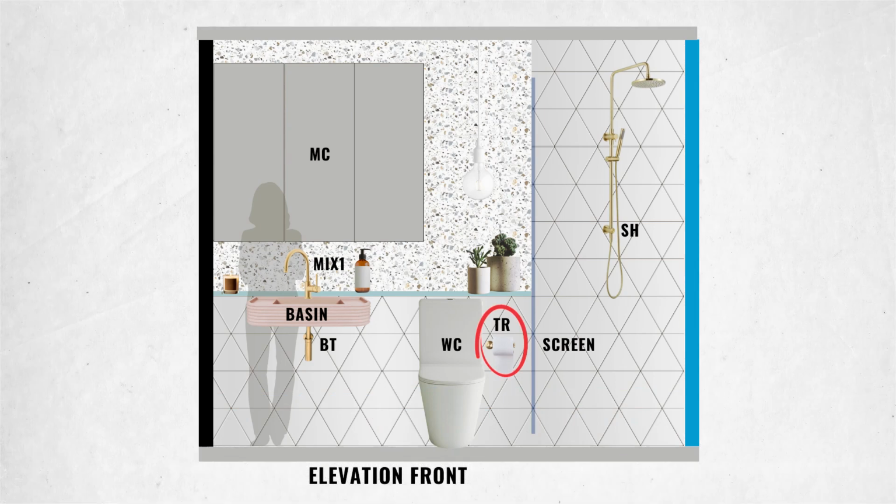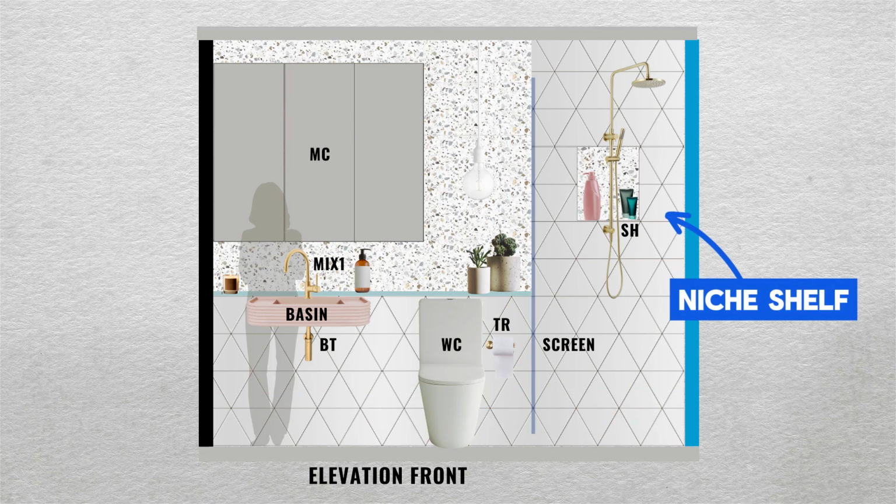holder, and we'll add a niche shelf in our thickened shower wall. Remember to install a shelf with 3 degrees incline so water can run off and doesn't pool. I'll select a frameless shower screen, another prefabricated item that is easily half the price compared with custom glass that is cut to measure, then toughened. Now, using the final sketch design, I can prepare a bill of quantities and start building up costs.